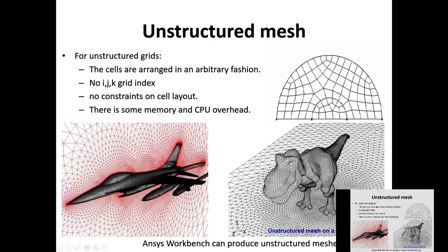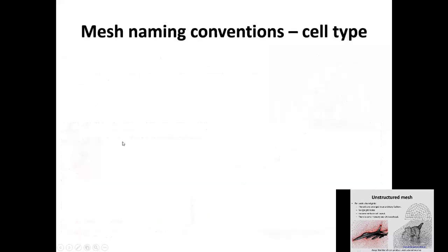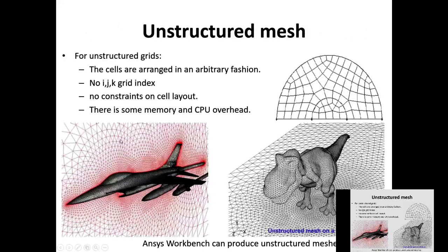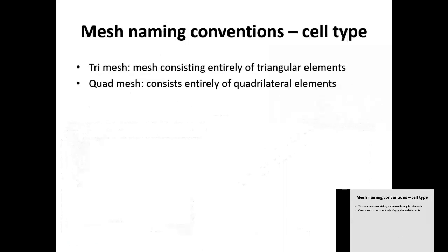So therefore, the near field, which means near here, you need a really fine resolution to pick up the sudden changes. Here, there are no sudden changes, so you are not worried about a fine grid resolution. So that is the answer to your question. Thank you.